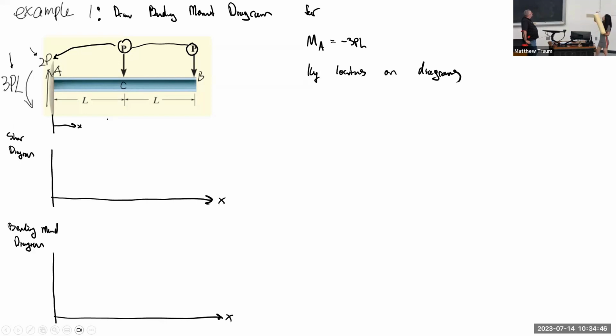So make sure that you are very clear about this, because when you do the shear force diagram, you need to put a sign there. If you don't put a sign there, it'll be wrong. So when you apply a force like this, this beam will bend in this way, and it should be negative. The bending moment applied by the wall to the beam should be in this direction, not positive as you said. Make sure that this sign is very important, because if you get it wrong, the whole bending moment and shear force diagram will be wrong.